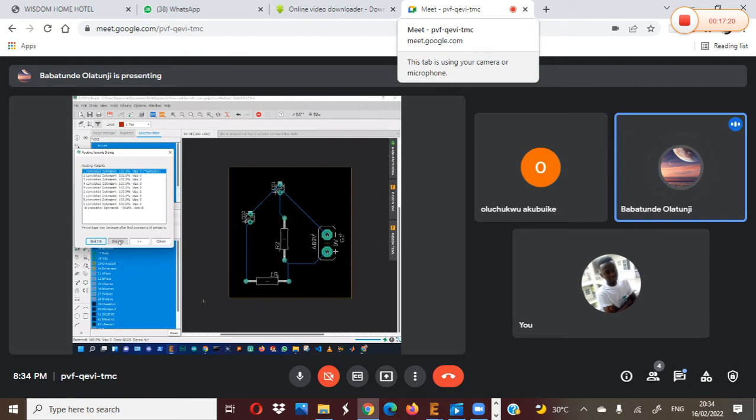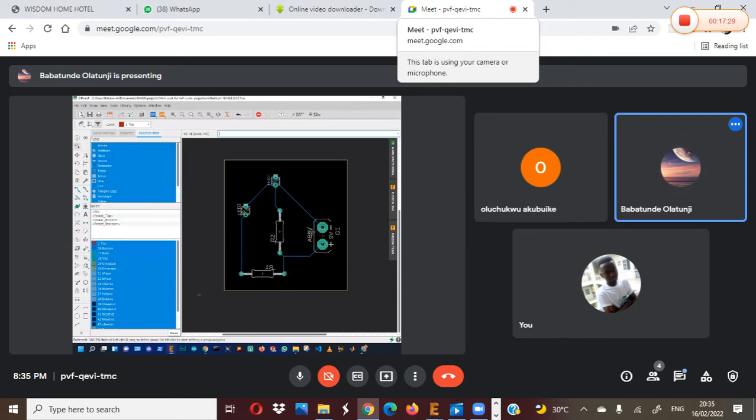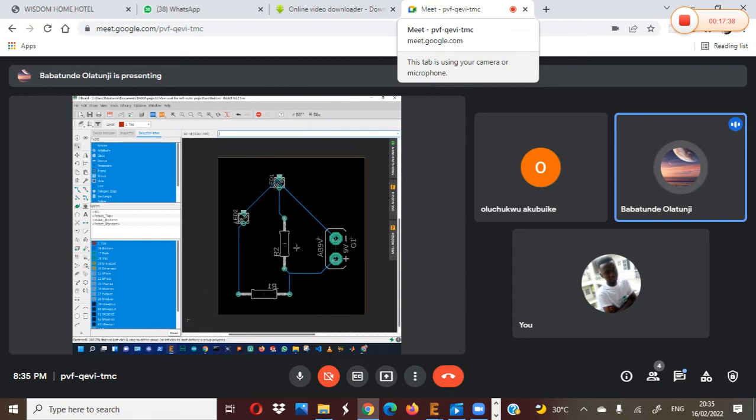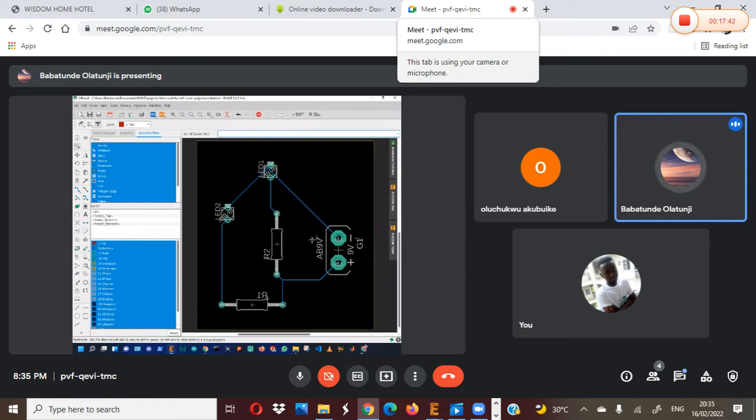Now can you see how the board has been routed? Yes. Okay, now click on end job. Usually, because this is a very simple circuit, you will not have issues with jumpers or the rest. But when the circuit becomes very complex, you might need to put some holes that later on you will drill and use jumpers to connect those components manually.